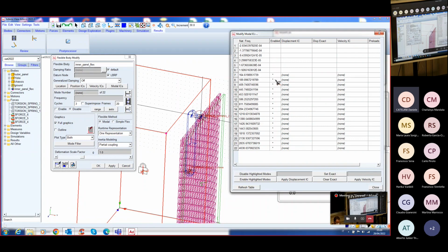The rest of the modes are activated, and they go from small level of frequency to very high level of frequency. And all these modes are important and fundamental. You cannot remove these modes due to the model content, because they are activated more or less depending on the boundary condition. If you have a fixed joint, all the modes participate.